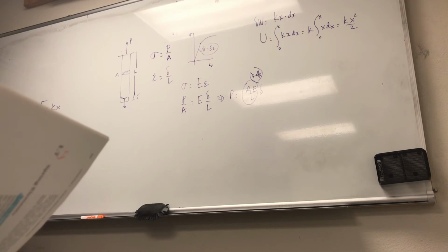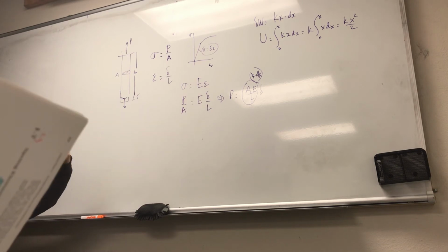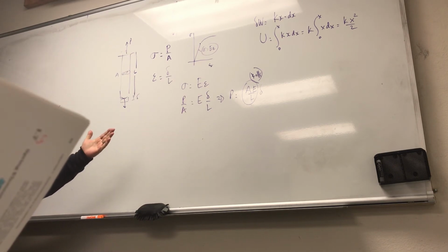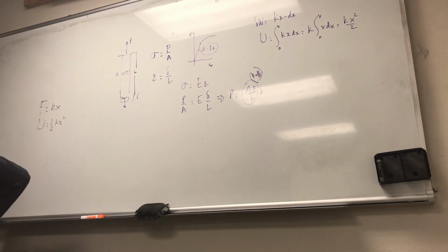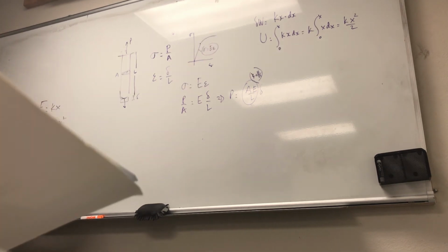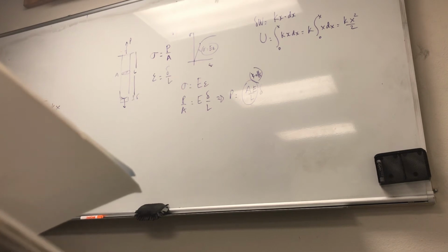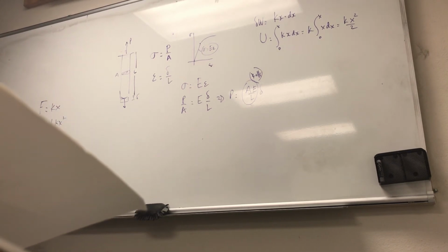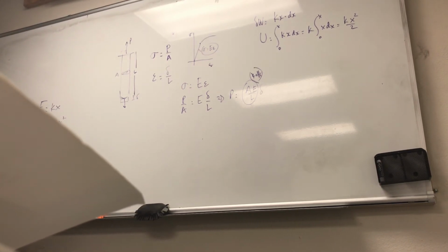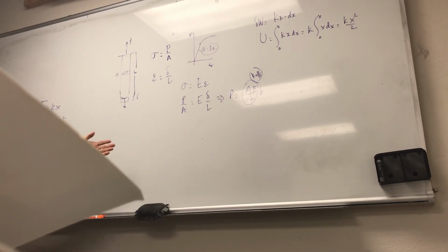equivalent stiffness. In other words, the only thing you need to keep in mind is that when somebody says, what is the equivalent K, in order to get the equivalent K, you need to write the equation in the form of what? Load equals some whatever group times displacement, right? Whatever that group happens to be is really the K, just like I did it in here. In fact, they had that example here, I didn't realize this.